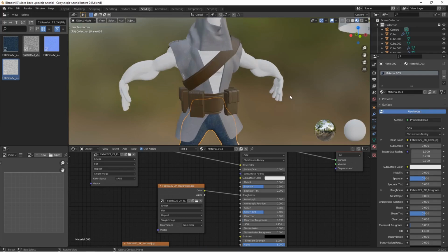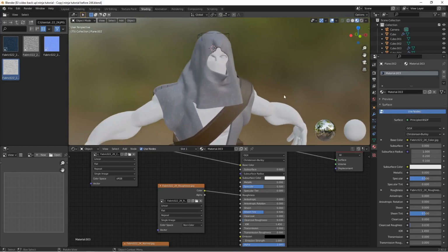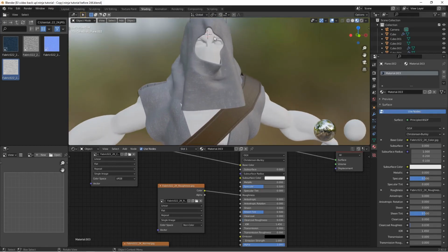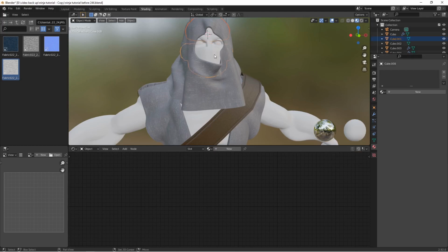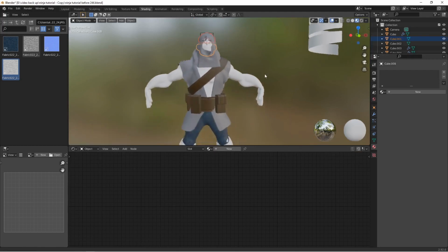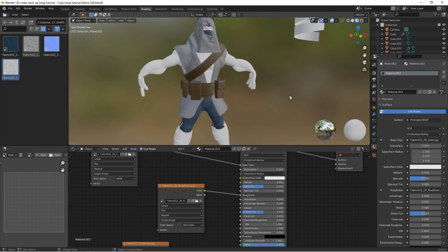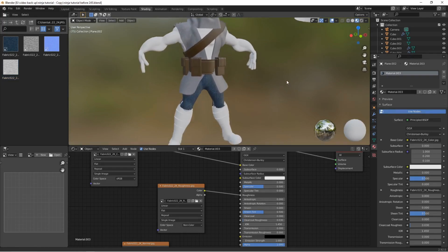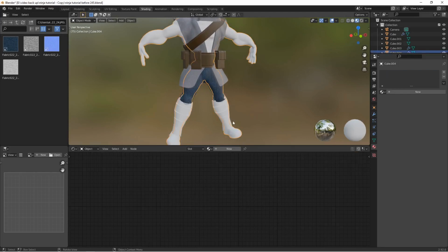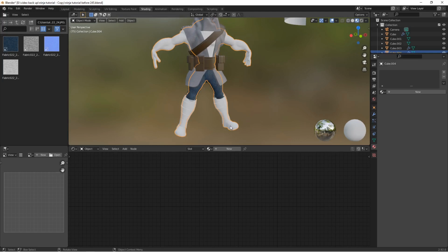Okay, I'm going to zoom in, hold Shift as well as the middle mouse button to pan. I'm going to select the top face mask, select the bottom. Hold Shift to make this active. Hold Control, press L, that brought up our Make Links menu. I'll select Materials. So now those materials are there. Okay, I'm going to pan and select here. Okay, so that is the body.